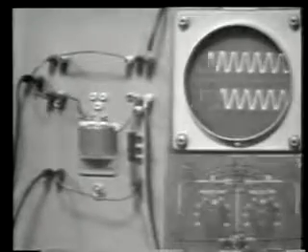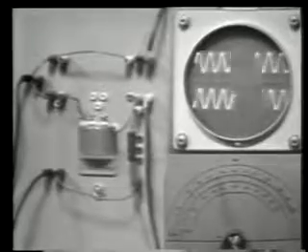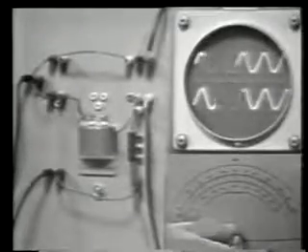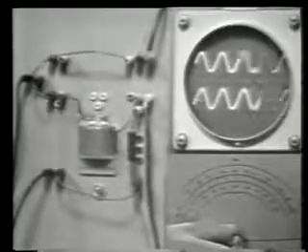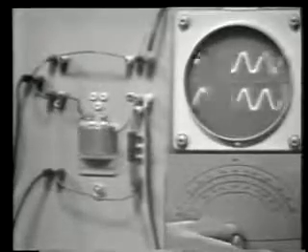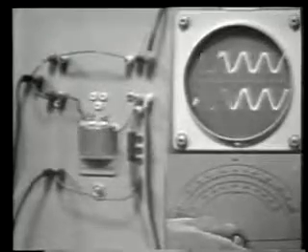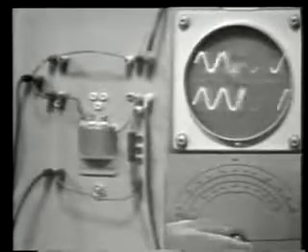Now let's check the overall frequency response of this filter circuit, the low-pass filter. Now you'll notice down at the low frequencies, I'm down around 200 hertz now, you'll notice that I do have an output. I have 10 volts on the input directly from the signal generator, and on the B trace, the lower trace, I show 10 volts of output from my filter circuit. So we're passing the low frequencies because this is a low-pass filter.